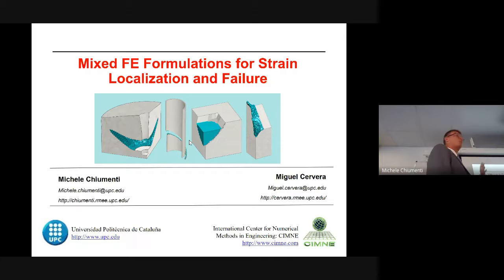The idea is to tell you what happens if you have some kind of strain localization during the simulation that you are carrying out. And this can happen either if you use plasticity models, as the one that you have been studying in this course, or if you are using some damage models. In both cases, you can reach the failure of the structure at different modes.